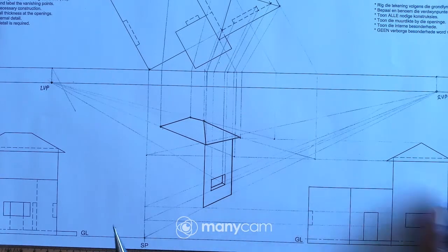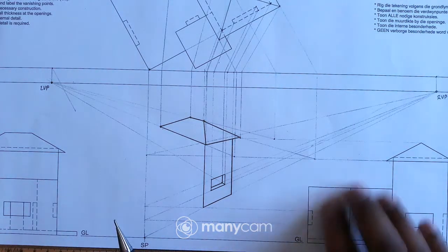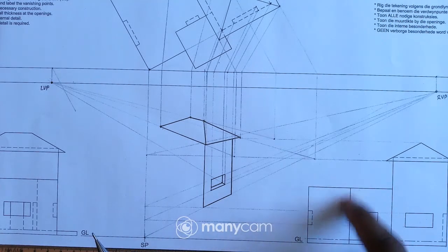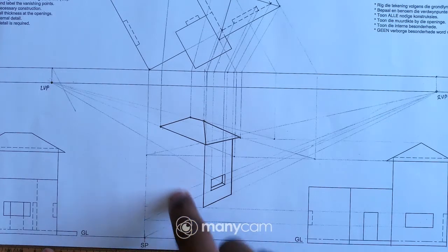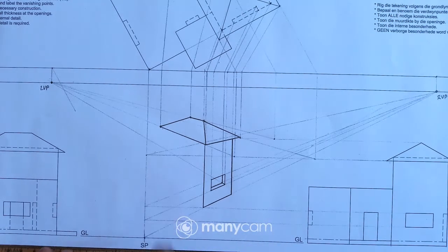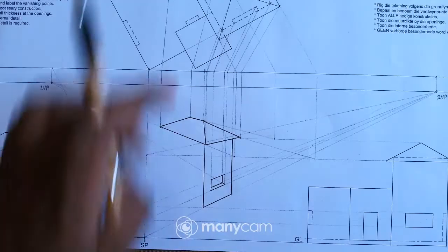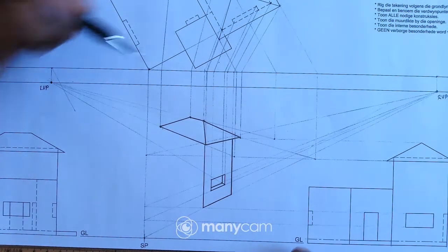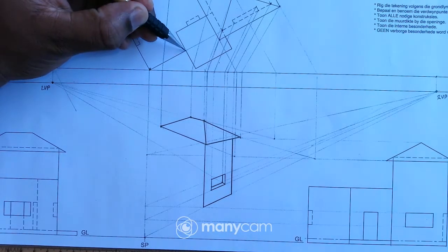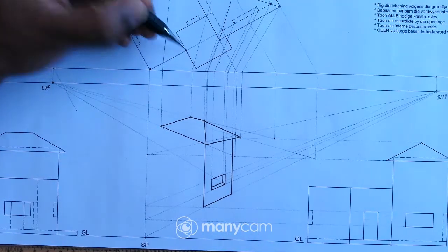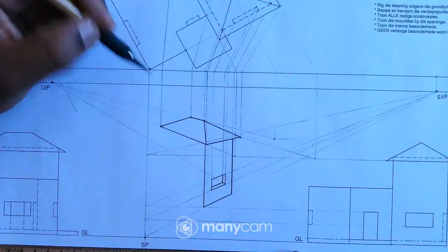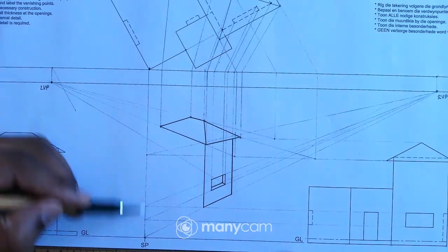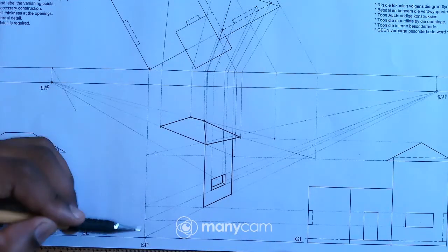So I just want to move to this part of the building, right? Okay, so I'll start by drawing this wall. That wall will be somewhere here, right? Okay, so this wall, where is it from the top view? This rectangle shape is right over there. It's from here to there, right? Okay, so obviously this point is on the picture plane. That means I'll just draw a vertical line there.